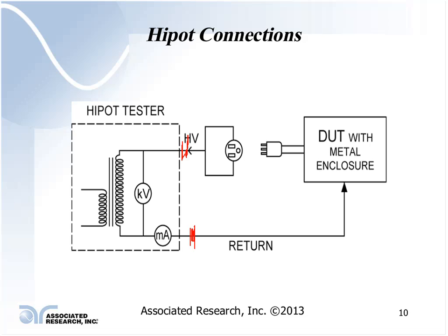So, how do you check for that? Well, you should be doing some type of daily fail verification test on your product. At a minimum, I would suggest shorting high voltage to the return. The best thing to do is, if you have a known bad product, you can put it in and test it every day, at least once a shift, then plug it in and run a test on it. Make sure it does fail.